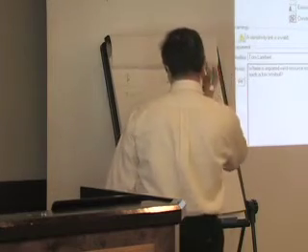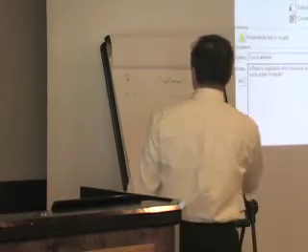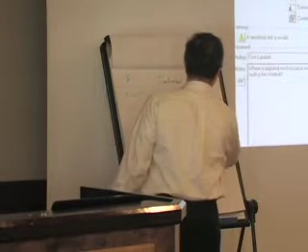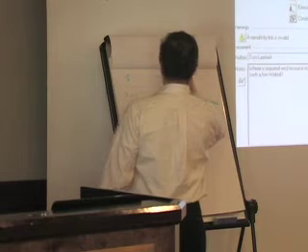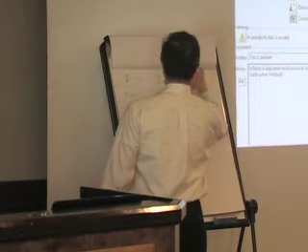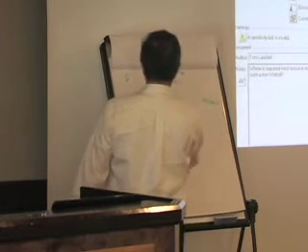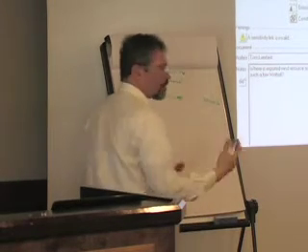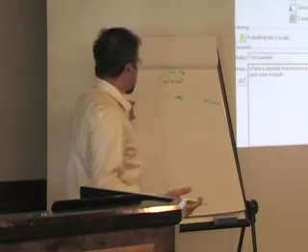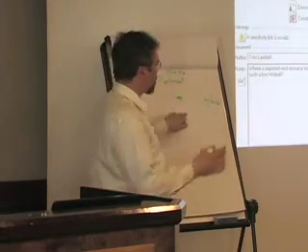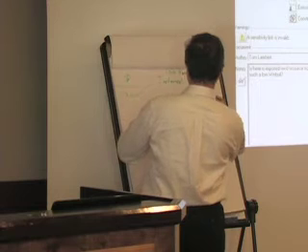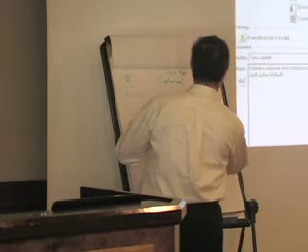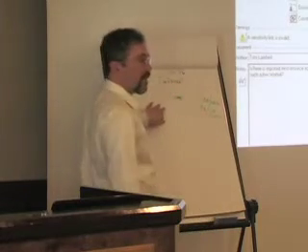Wait. Excuse me a second. Let's say you've got a 100 kilowatt generator. And you have to spend $300 on an oil change, filters change, et cetera. It's going to cost $300. You have to do it every 100 operating hours. I'm just making up these numbers. That would be $3 per operating hour. So that would be the number to put into Homer.